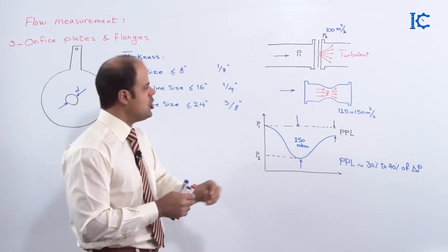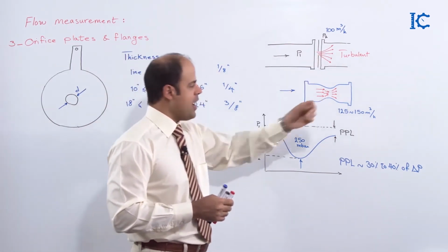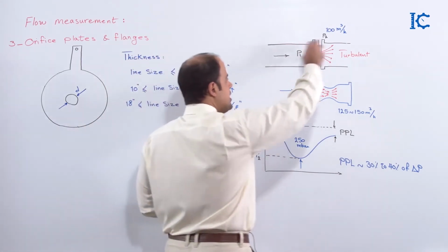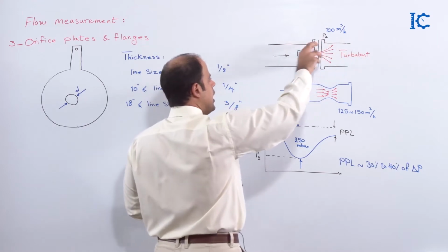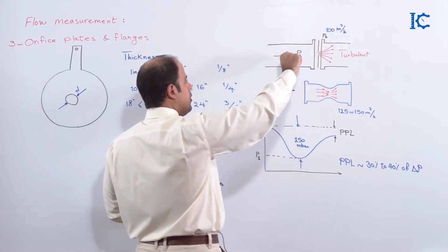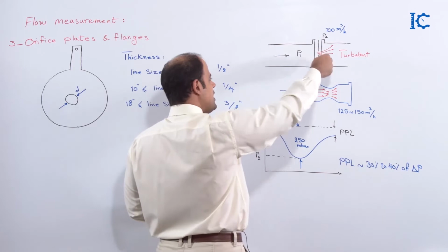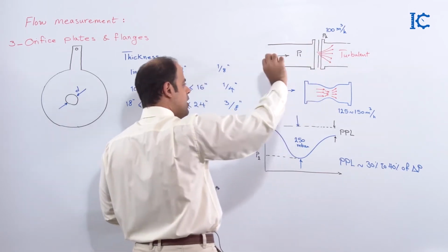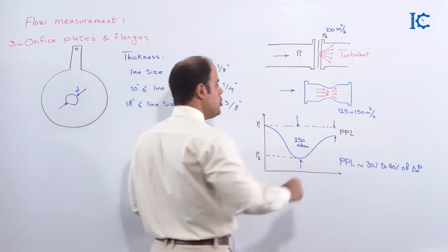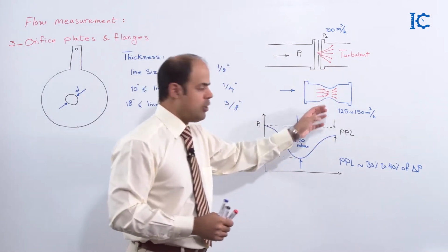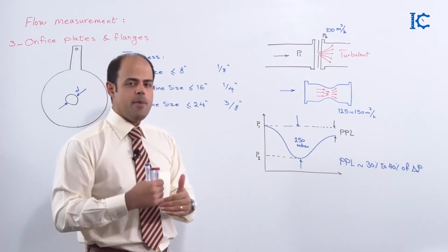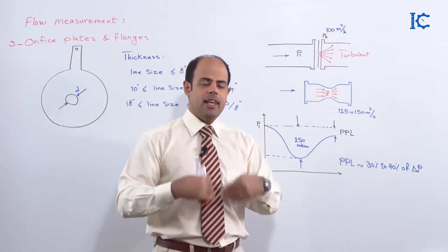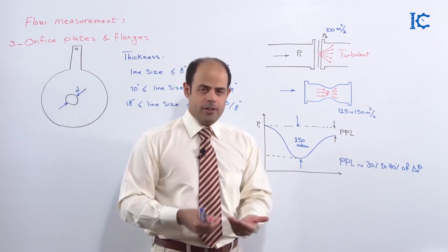About the other things, to some extent we can change the shape of the orifice to become a little bit like a Venturi, not to have this rapid profile out of the bore so fast. By changing the bore a little bit, we can reach this shape too, but not the same as the Venturi. But the pressure recovery, and the flow becoming linear and laminar again, would be better than it used to be.